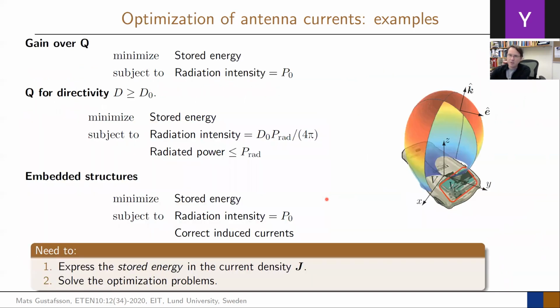So you can modify this to quite a lot of different cases. We will go through this a little bit quickly. And then in the same way, if you remember back when you did your array antennas, what we did is that we learned a way to synthesize radiation patterns. We learned the Dolph-Chebyshev method, binomial array, uniform array. They had some properties with side lobes and so on. But we also learned that a more general way of doing this was to rethink the problem and instead ask, what would I like my array to do? And then formulate that as an optimization problem.